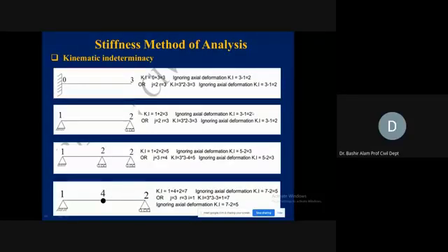If you want to go by the equation, now most of the time people forget the equation. So if you forget the equation, this is the option: you go by the observation. Now, J is equal to 2, this left hinge support joint and the roller support joint. Reactions are 3. Which ones are those 3 reactions? One vertical at this left support, one horizontal at this, and then one vertical here.